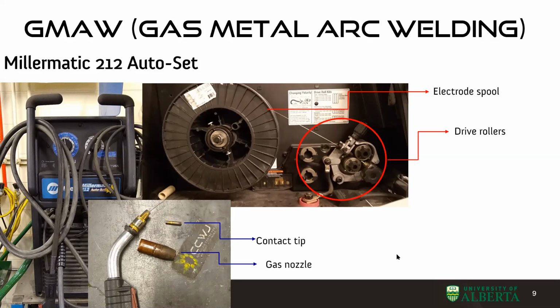It doesn't have that temperature profile. So the start is a fairly traumatic event in welding. And in addition, we first started and then we did motion, but it's true what Wesley said too. If you start moving before you start feeding, when the electrode comes down and touches, then it rubs, and that will help.